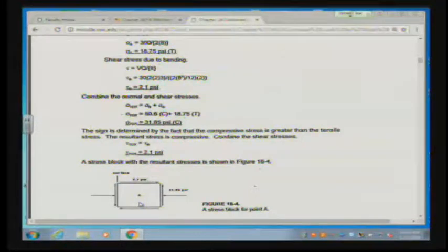Now the one thing that I also want you to recognize is sigma is an axial phenomena, happens on a single axis. So you'll notice that 31.85 psi is counteracted by just two arrows. In other words, pushing this together prevents it from moving. However, with tau, what you'll see is there are actually 4 arrows.